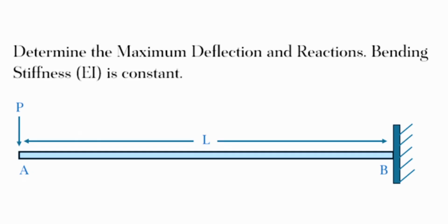But you know what? Going back to FEA, in this case, these problems are straightforward. You start with boundary conditions, and then you start assembling your global equation. And I've said it in previous videos too, for the whole class, you either know one or the other, but you never know both, and you never not know one, if that makes sense. So in this case, if we know deflection at one location, that means we don't know the force. And if we do know the force, that means we don't know how much it's gonna deflect. So you'll see what I mean. Let's go ahead and get started.